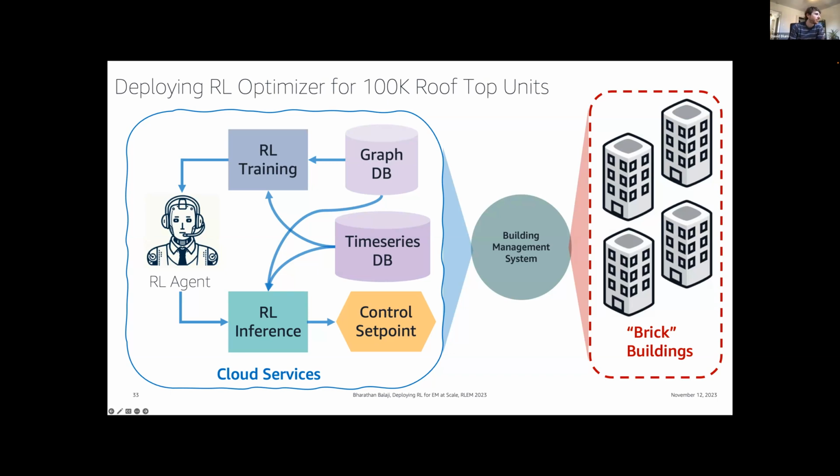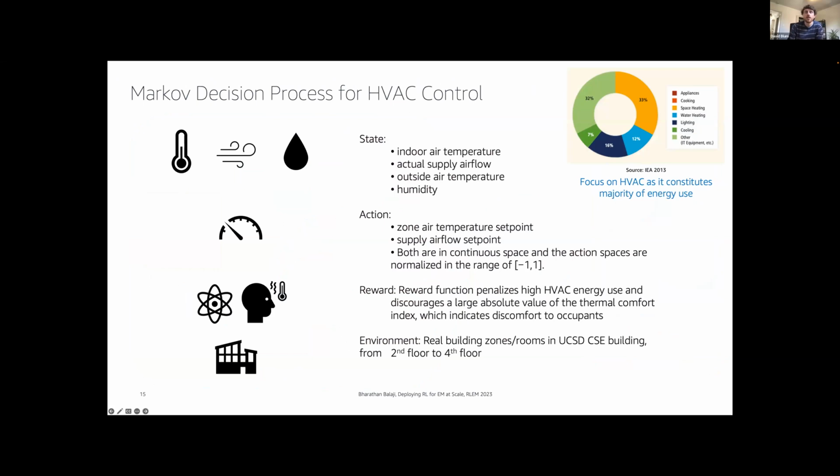And then on the previous study at UCSD, can you describe once again, what did you control in that study? Were they individual VAV boxes of individual zones, or was it some higher-level, system-level control? Yes, it was individual VAV boxes. Okay, so those two studies are controlling specific aspects of the system individually, the economizer loop in the rooftop unit, or single zones at a time with VAV boxes. I'm curious about your impression on using RL for more system-level control in real buildings, and where the state of the art is. If you have a multi-zone building and you want to control the rooftop unit to set the supply air temperature and static pressures to optimize the entire building operation, I'm just curious where that sort of control stands, if you know.